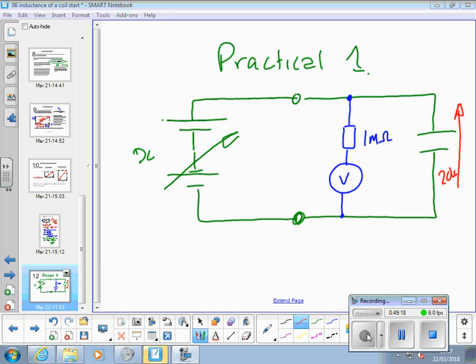20 volts, say. Now, this power supply here is one of these. Remember what you're going to do: you're going to charge it up to a given voltage, chosen by you, and then you want to discharge it through the meter. So the capacitor is charged. If we just switch this off, there's an internal resistance and it'll discharge through the power supply. So what we need to do to discharge is take one plug out.